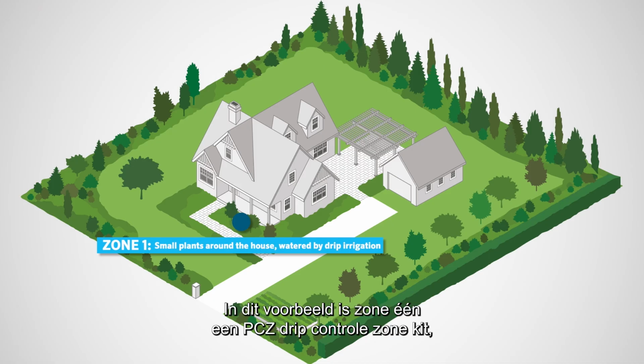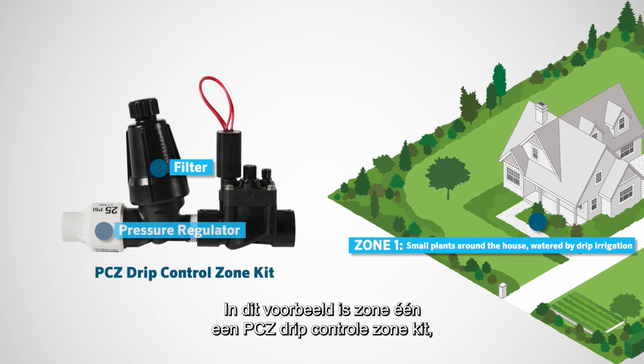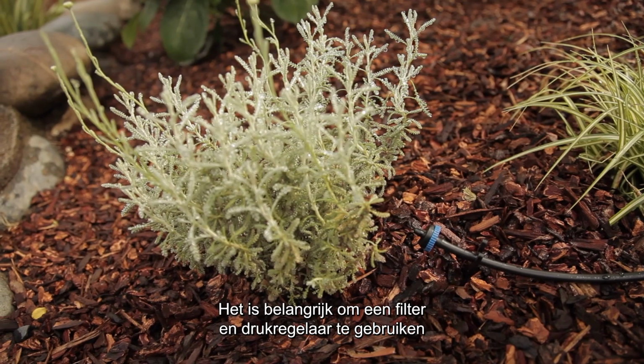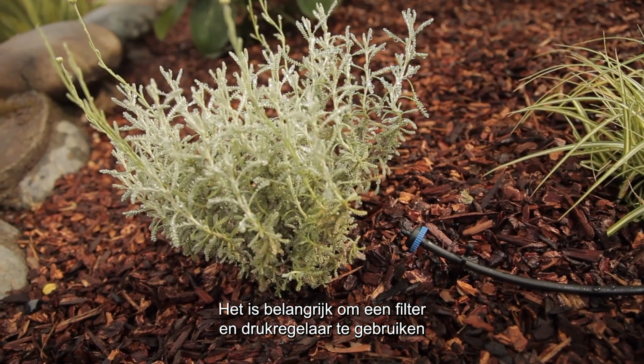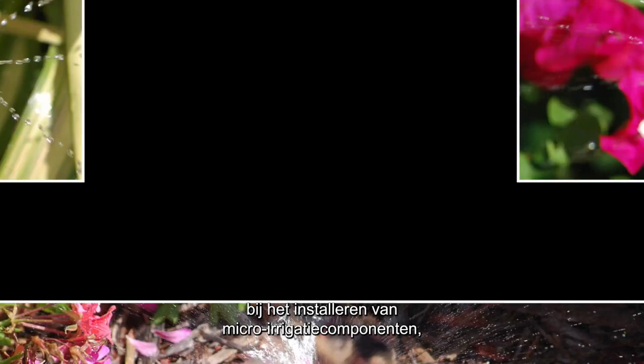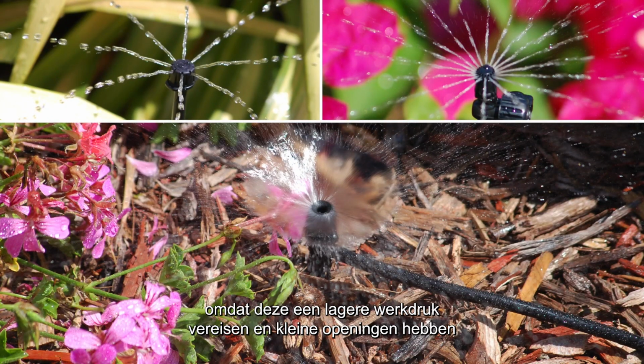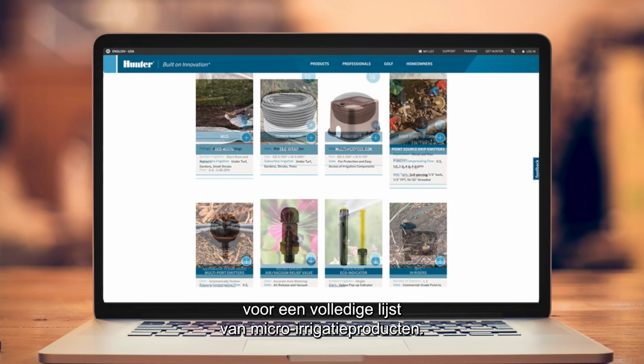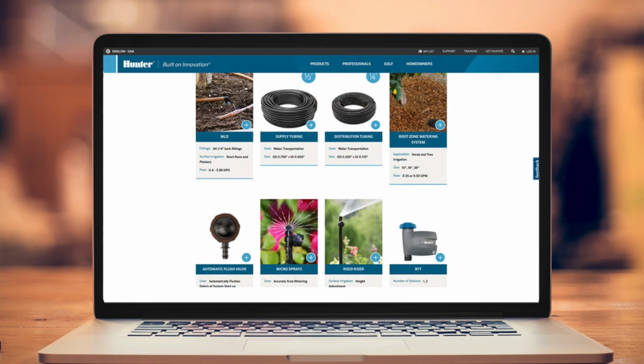In this example, Station 1 is a PCZ drip control zone kit that includes a filter and pressure regulator. It's important to use a filter and pressure regulator when installing micro-irrigation components, as they require lower operating pressures and have small openings that could become clogged with debris in the water. Refer to the Hunter catalog or Hunter website for a full list of micro-irrigation products.